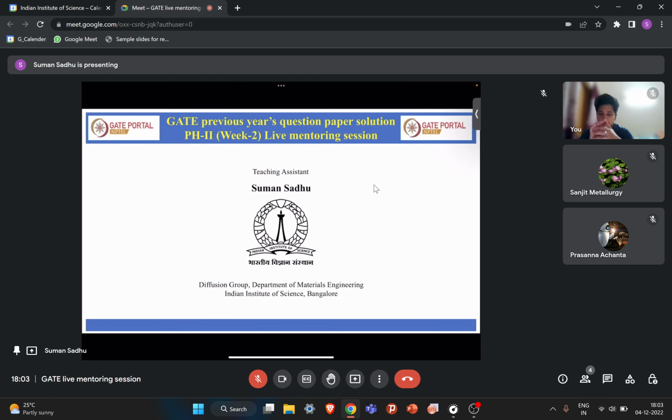Like in this video also you can see. So this is the pine oil and this is the water. Now you are putting the powder ore in this chamber, and then you are passing the compressed air through this blower. Then this air is creating froth in the oil layer.